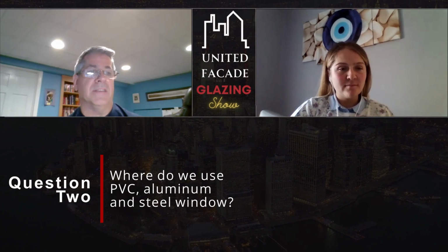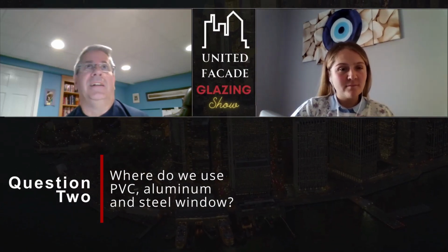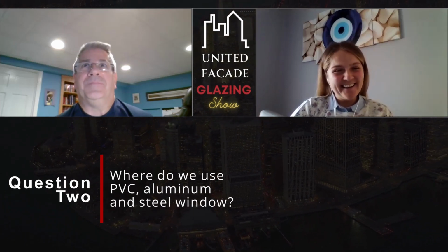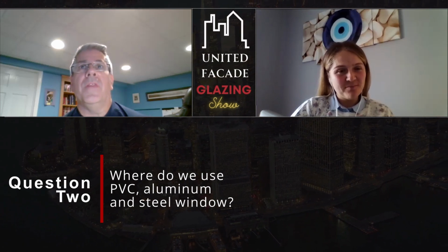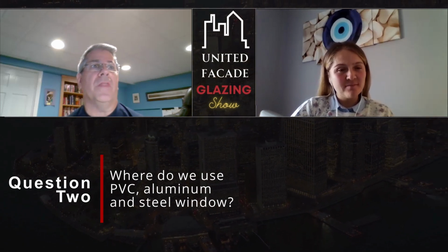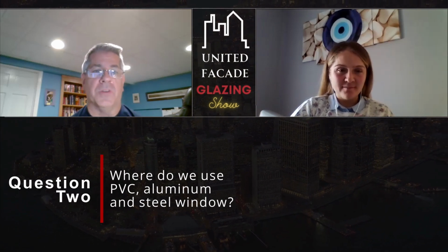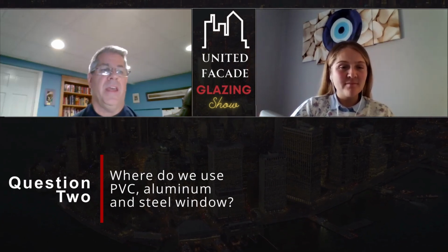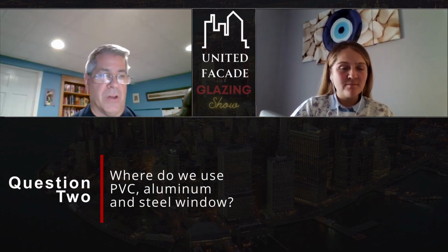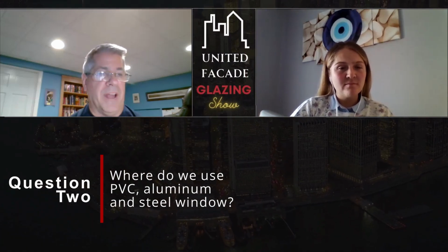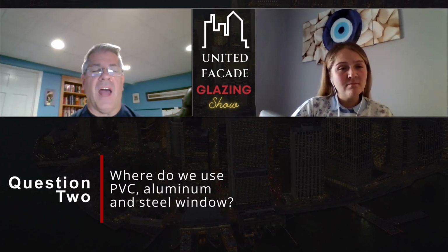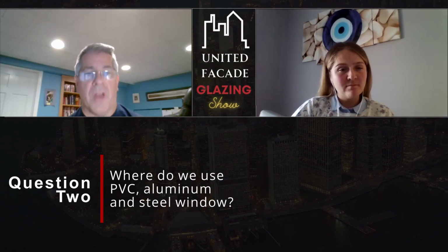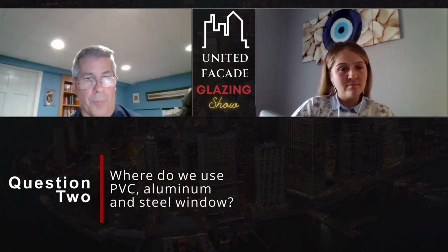A thermal break is a plastic, wow, we're getting technical now. It's just going to be a split in the aluminum that's designed by an engineer that will stop the cold at this point, because it's a different material. So once it doesn't have a continuous path through aluminum from outside to inside, it has to pass through this material, which we call the thermal break, which is a plastic type of material that will stop the cold from transferring to the inside. Aluminum windows, you're able to do that with. You cannot do that in the steel window.